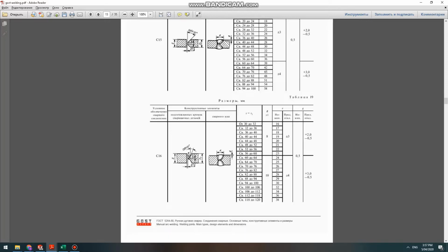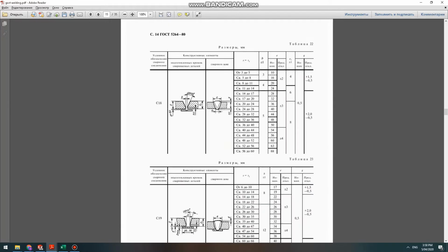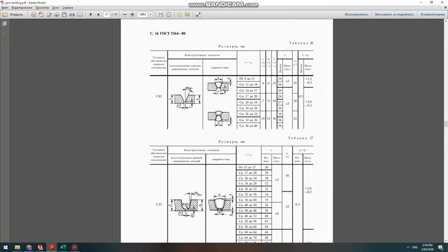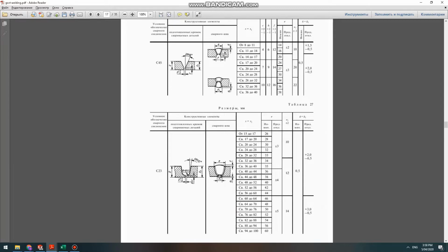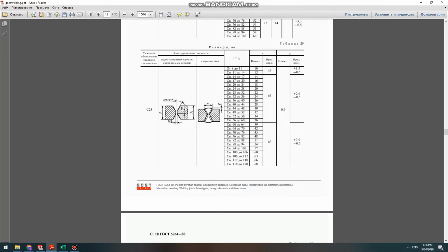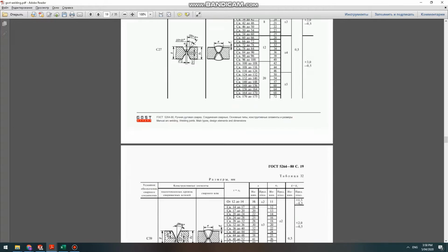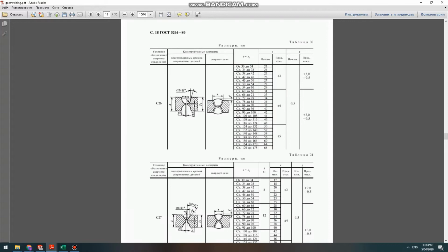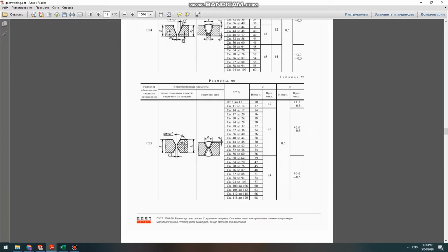So why double-sided? Why is that the case in this geometry? It's because the operation they perform, the bending of the bottom, it's a very advanced operation. If you do one-sided welding, it may damage your system and it will create issues during the welding testing. So you have to do double-sided welding, and for double-sided welding, I would suggest C25.